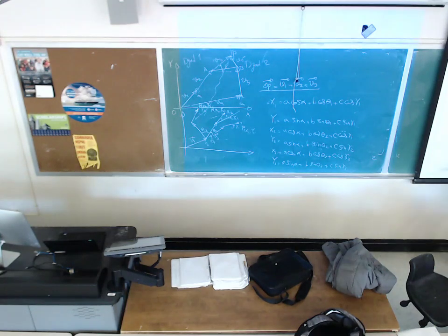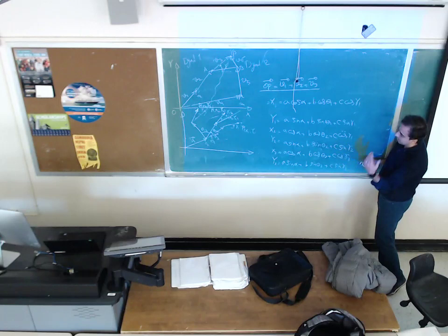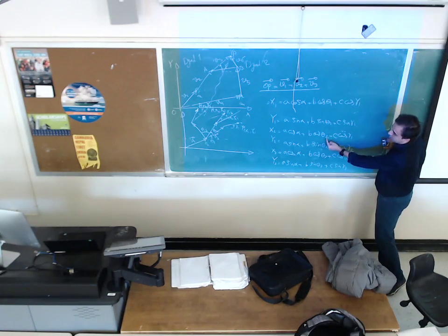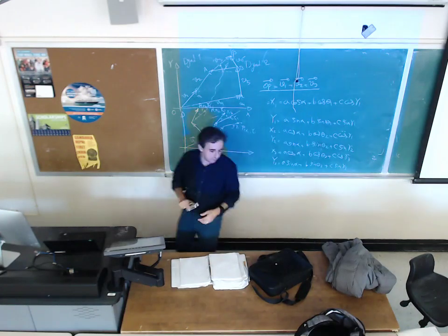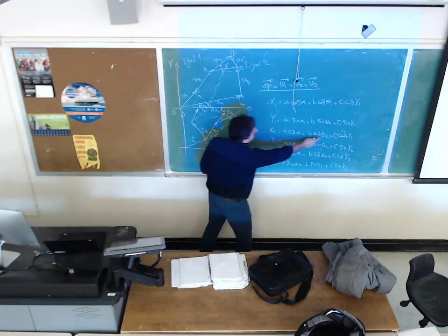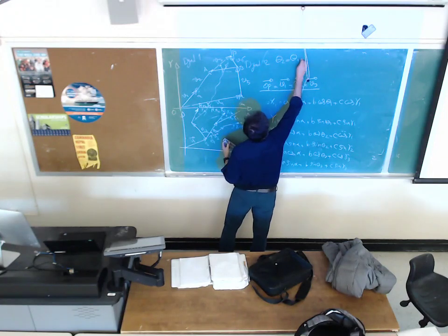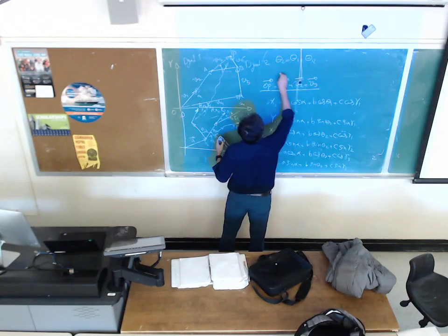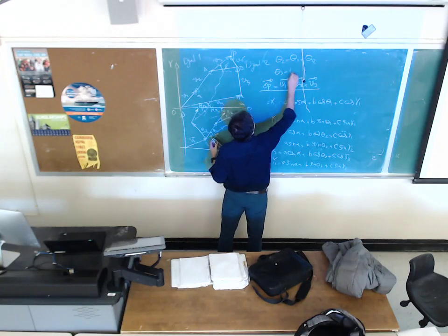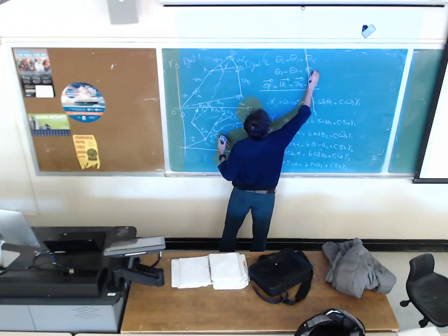Then, as in function generation, I'm going to write each angle with respect to its first precision point. So theta 2 can be written as theta 1 plus theta 1 2. Theta 3 would be theta 1 plus theta 1 3.